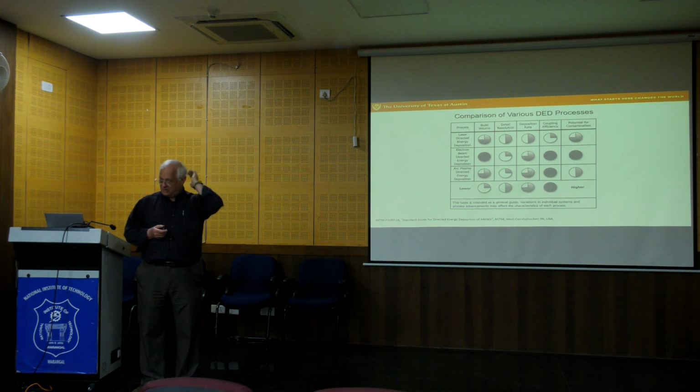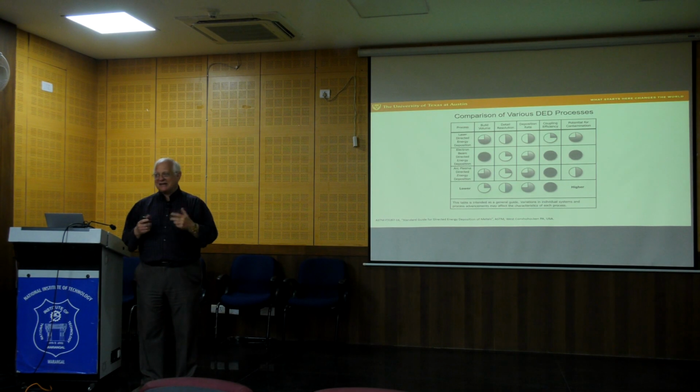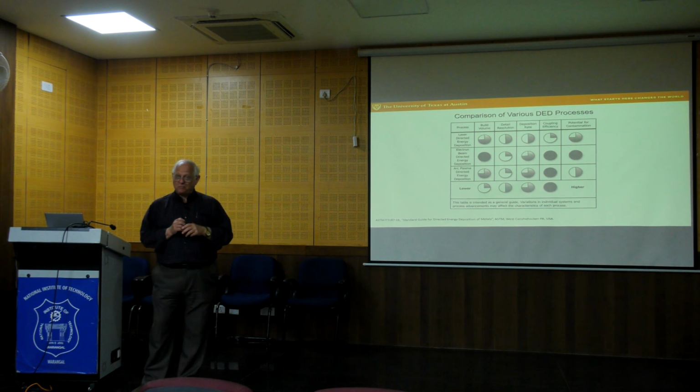Even though a laser may couple to a metal with, say, maybe 20% efficiency, in a powder bed the laser penetrates into the powder and kind of rattles around. 20% gets absorbed, 80% gets reflected, but that 80% pops against another powder particle and supplies 20%. Because the laser beam bounces around in the powder bed, we can actually get better coupling.